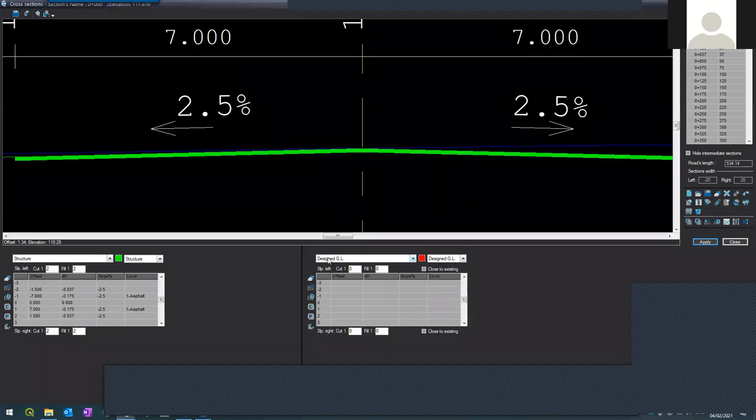The design ground level. Now I want to enter the Earthworks. How do I do it? This is the 0, 0 point. I know that my total structure is 60 cm. So I'm starting at the 0 point and I'm going 60 cm below. So it's minus 0.6 because it's in meter. What I did, went from here 60 cm. This is where I start my Earthworks.